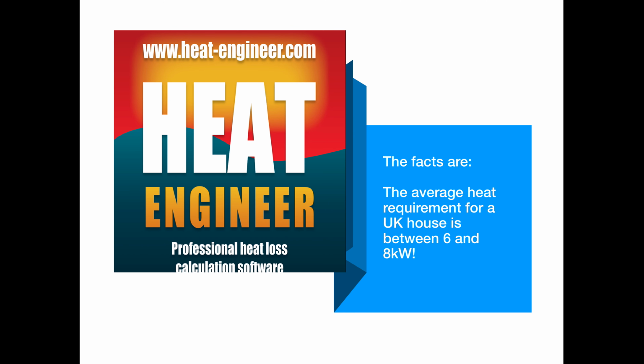So these are the facts. The average house heat requirement for UK properties is between 6 and 8 kilowatts. Not, as we've been led to believe by wrong calculations in the past, anything up to 20, 30, 40 kilowatts, or even future-proofing buildings by putting in a 40 kilowatt.